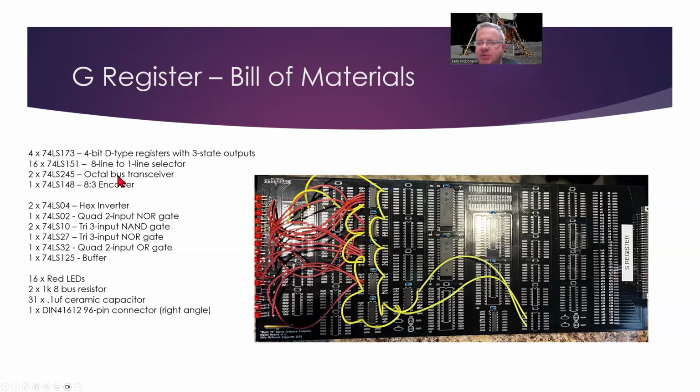So for the next episode, before we get into our SQ register, which is the sequence register, and that's actually how we decode instructions and determine which control pulses we need to be generating based on the actual instruction, I'm going to cover what we call branch control. So the AGC has basically 2 branch bits, BR1 and BR2, or is it maybe BR0, BR1? Anyway, there's 2 bits that determine basically branch instructions.